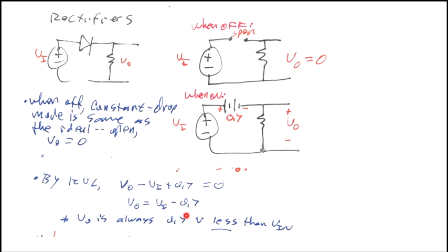If we used a Schottky diode, it would be V in minus 0.25. And in a lot of circuits, that actually makes a difference in the efficiency. So in a lot of circuits, we might use a Schottky diode to get a smaller voltage drop.